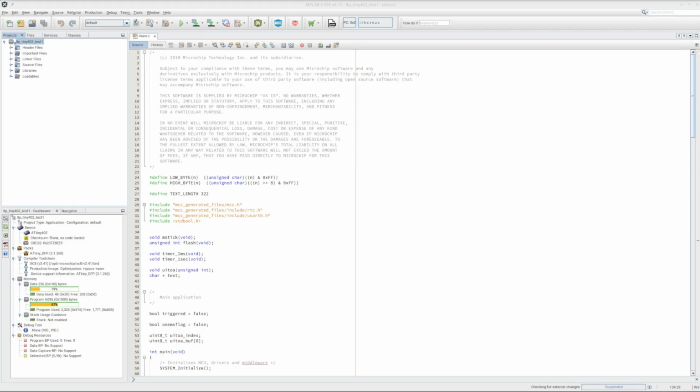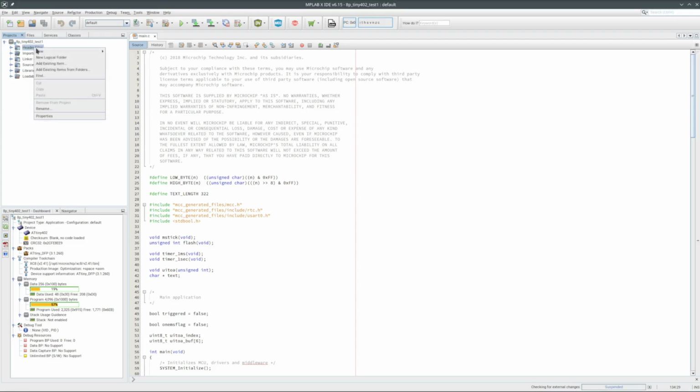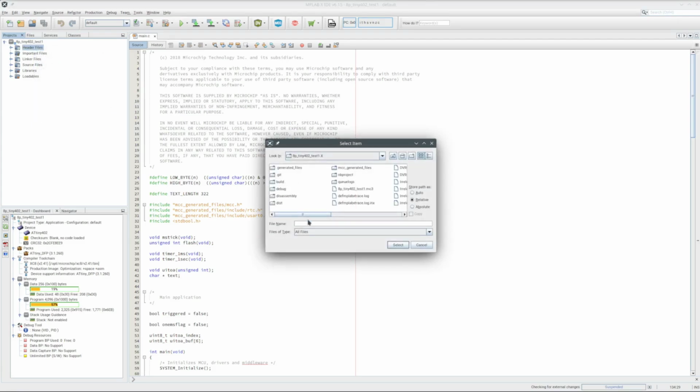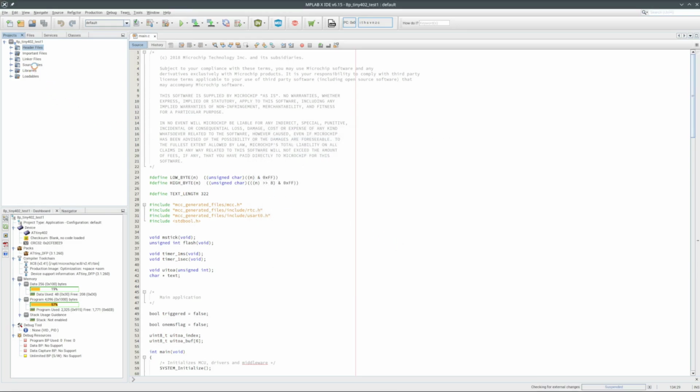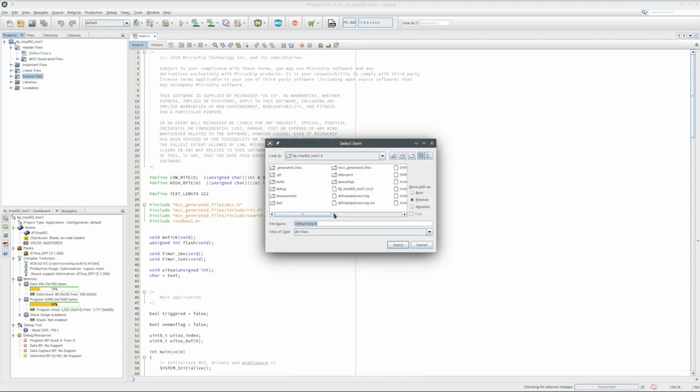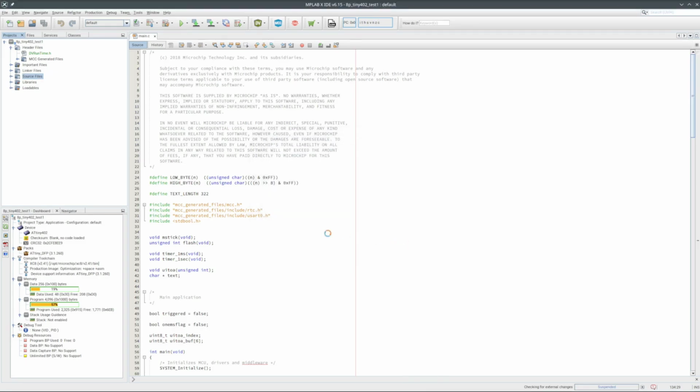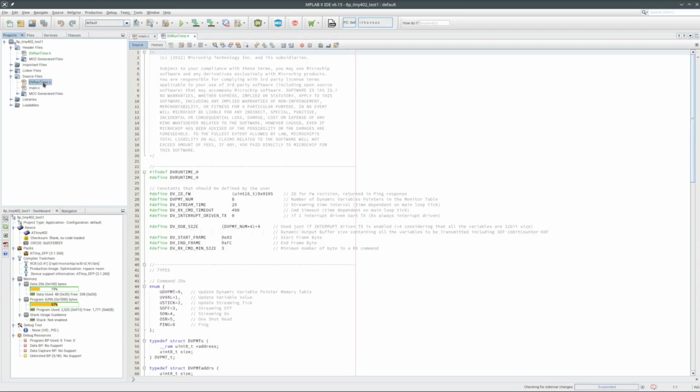There is not a lot of information in the data visualizer's user manual about the DVRT protocol or how to set it up. It does point to some example code to use, but there seems to be only one example, and it's for a PIC16F18446 project. Hopefully that will be enough. The user manual does say to include the DVRunTime.h and the DVRunTime.c files into your project. I'll put the files in my Tiny402 project.